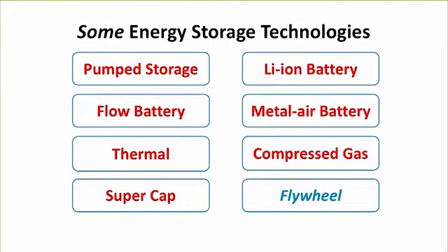Okay, so example technologies are pump storage. This is basically gravity storage with water. It basically entails 2 lakes associated with a dam or 2 dams, and the ability then to pump water back uphill as well as to generate with water coming downhill.